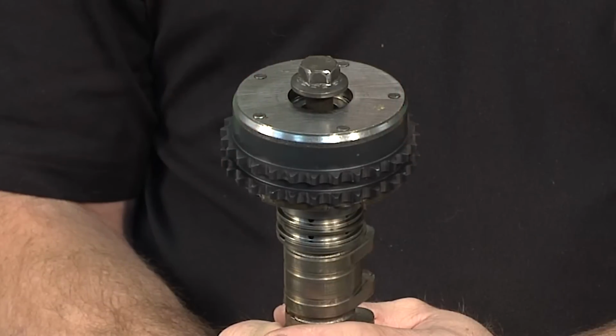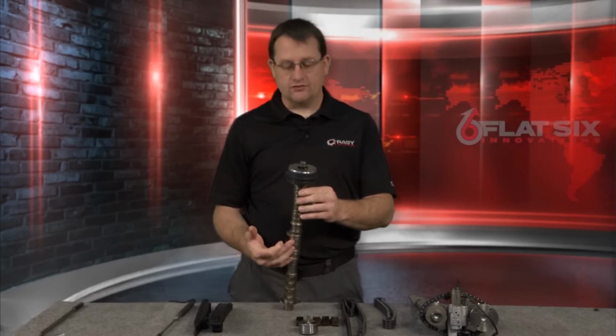Okay? There's another aspect of this where a very large bolt goes through the center of this and holds it to the camshaft. Early three-chain engines, mostly in 2002 996s, had a problem with this slipping on the intake camshaft. So let me grab a camshaft and show you a little more about what I'm talking about. I've grabbed an intake camshaft here from a three-chain engine. This would have been out of about a 2002 to 2003 996.